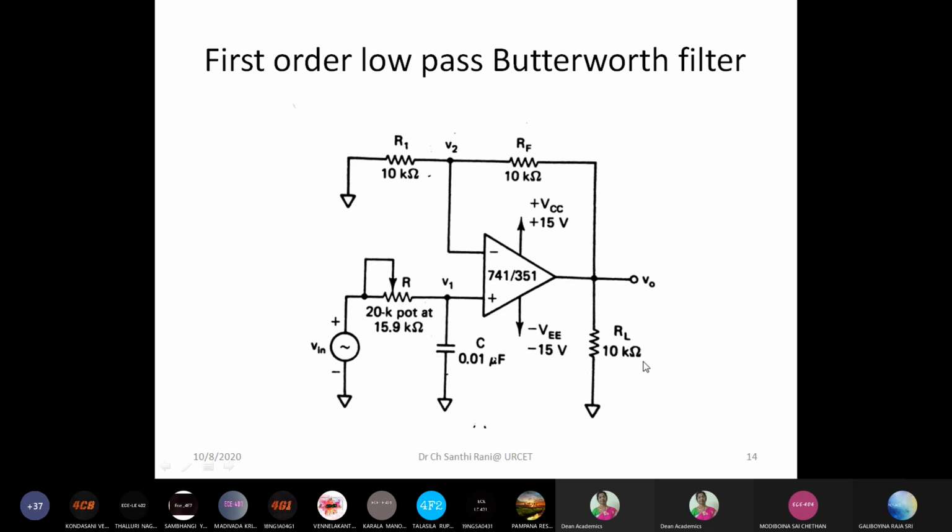That's all. And of course the load resistance, just name it RL: RF, R1, RC, input. So now, if I ask you to draw the circuit diagram of a low pass filter, you can draw it, and without showing the high pass filter, if I ask you to draw a high pass filter circuit, we just draw it by exchanging the components R and C. Am I correct or not? Right? I think you are responding positively.